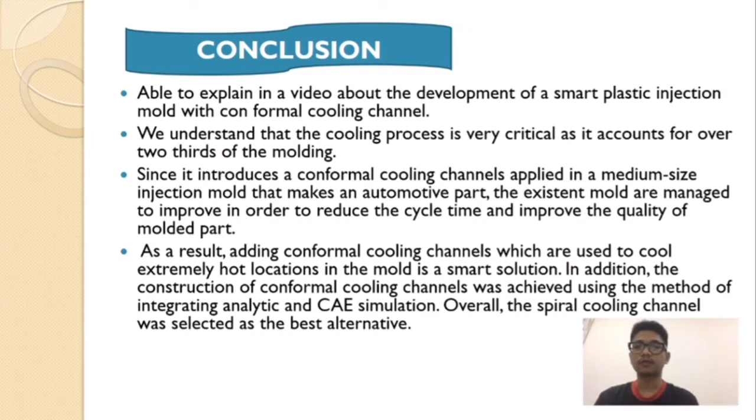In addition, the construction of the conformal cooling channel was achieved using the method of integrating analytic and CAE simulation. Okay, for the last one, overall the spiral cooling channel was selected as the best alternative.